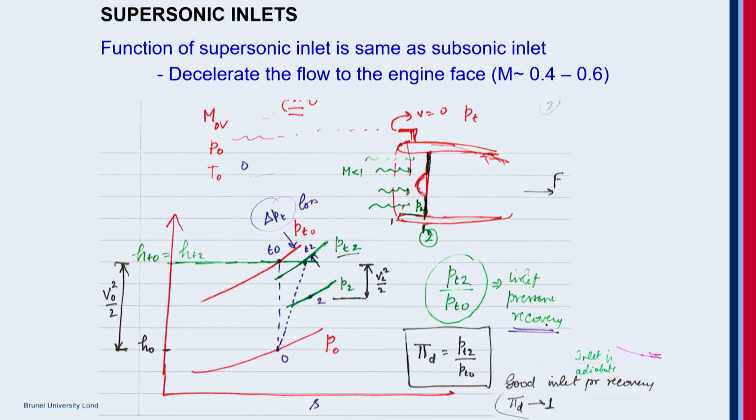So we looked at these supersonic inlets. We looked at the inlet in subsonic applications in the very first lecture. We looked at the inlet pressure recovery, and we also solved a problem where we saw that the inlet pressure recovery improves when we have more shock trains. So if you decelerate the flow over multiple shock trains, then the inlet pressure recovery improves.